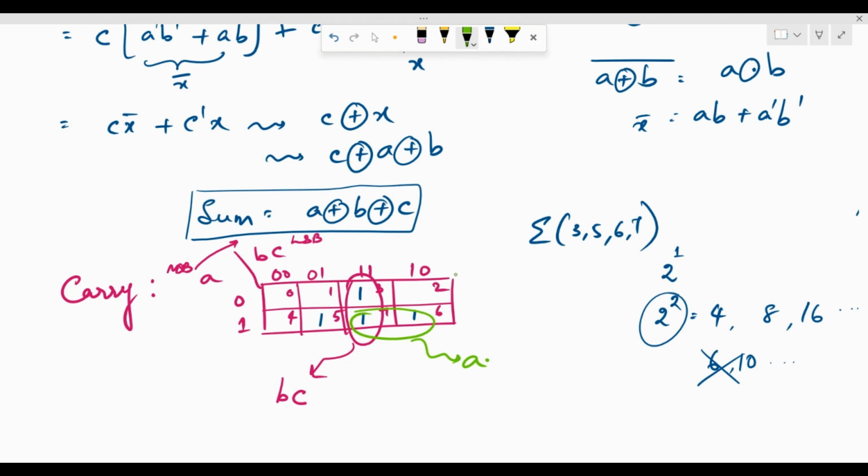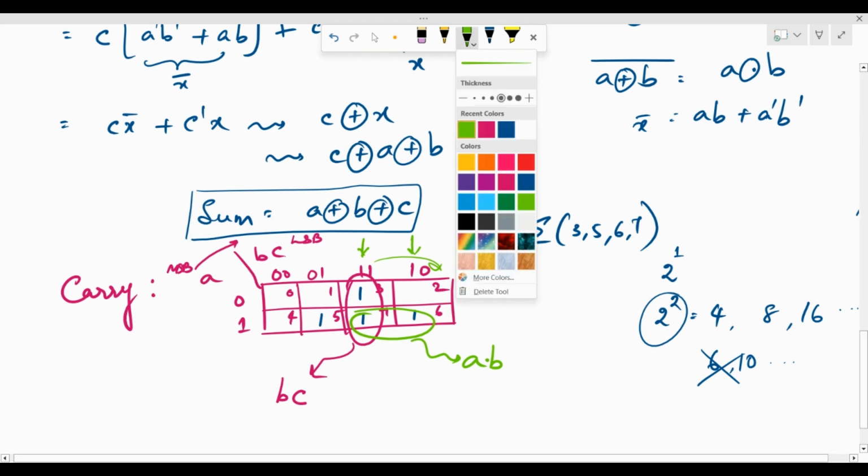So let's analyze the columns. It is spread across this column and this column. So this is 1 1 and 1 0. If we closely observe, B is consistent at 1 for both the columns, but C is changing from 1 to 0, right? Whatever is common, we are going to retain. That is B, not C, because C is changing. Let's try a third group.